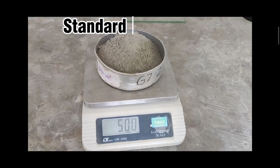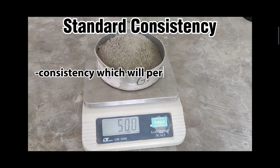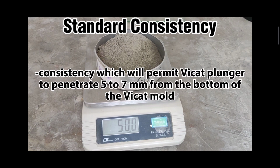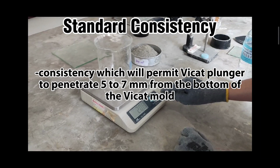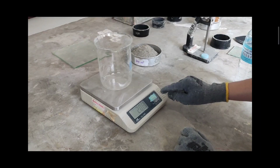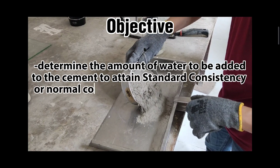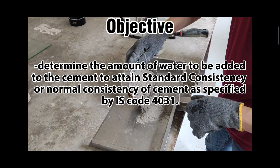The standard consistency of cement paste is defined as that consistency which will permit the Vicat plunger to penetrate to 5 to 7 millimeters from the bottom of the Vicat mold. Therefore, by definition, the objective of this test is to determine the amount of water content that is to be added in cement to attain standard consistency or normal consistency of cement.